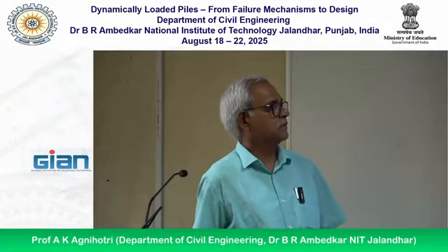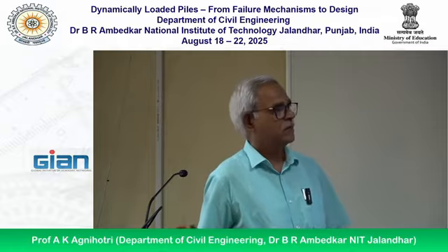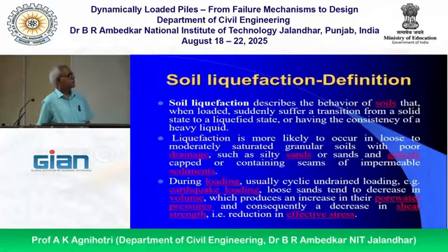Soil liquefaction, as already explained, describes the behavior of soil that, when loaded suddenly, suffers a transition from a solid state to a liquefied state, having the consistency of a heavy liquid. Liquefaction is more likely to occur in loose to moderately saturated granular soils with poor drainage, such as silty sands or sands and gravels capped or containing seams of impermeable sediments.